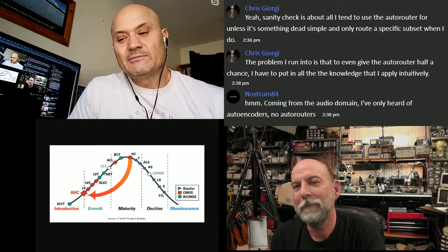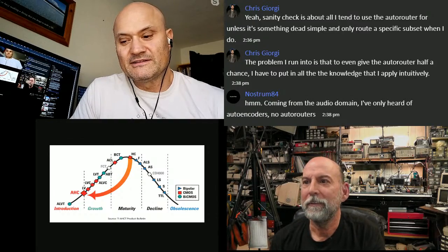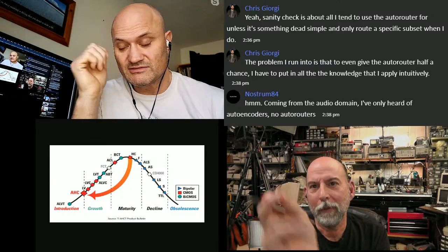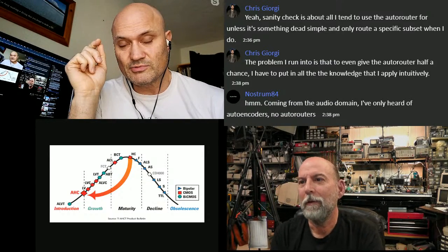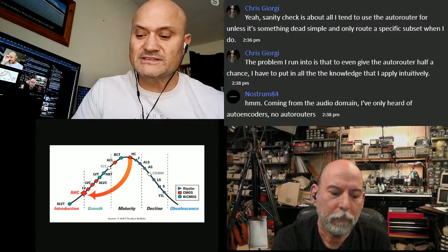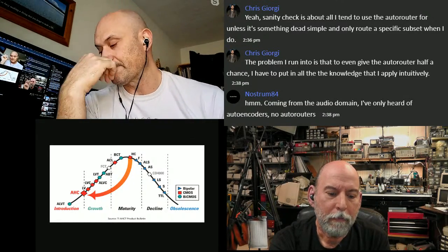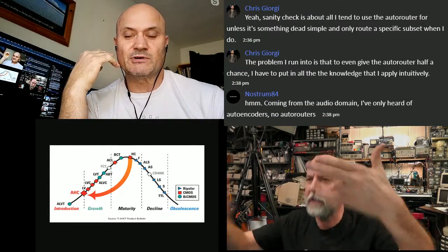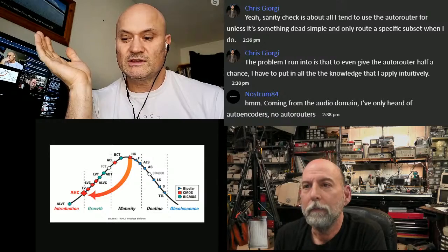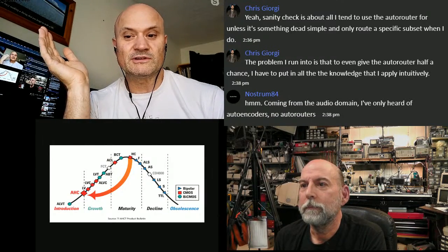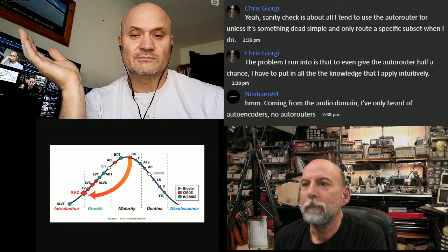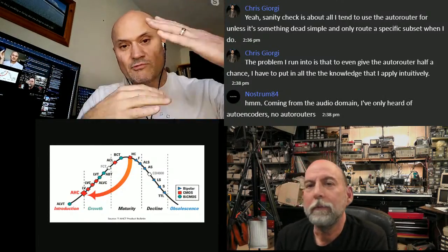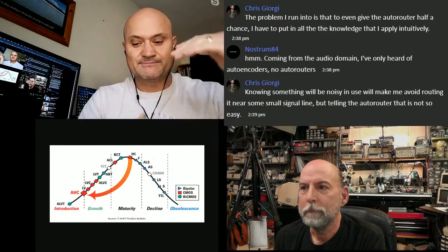What you want to enable is follow mouse trail, or as you're routing the board, just change modes. Switch off of hug and push, or use hug and push. See, the reason it does that is the assumption is you want to maintain as much routing channel room as possible, because presumably you've still got a lot more work to do, and you don't want to be pushing and shoving and using all that compute power to slow down the process. Or if you're doing low quantity, you want to keep room available for future routes.